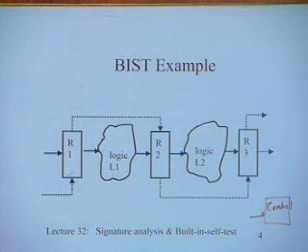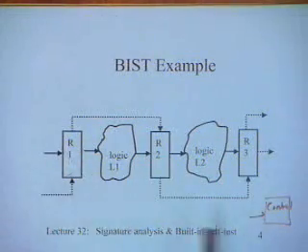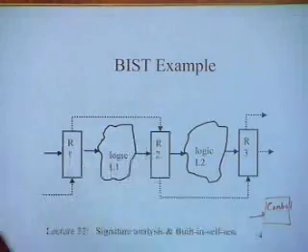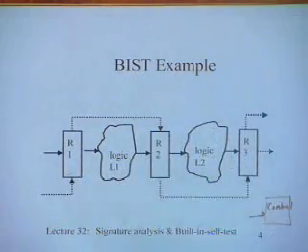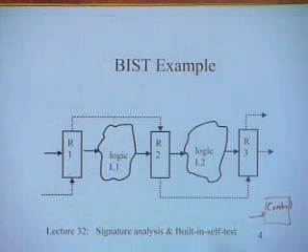Typically the way the design community works is you do the design and then introduce the testing on top of it. That is, you make the design, then you replace these registers, introduce the scan paths, and only the final placement and layout you do after introducing that. But increasingly people are also looking at techniques called design for testability. We are not going to talk about that in this course now. But basically the advantage is you can try to integrate it so that your testing overheads later on become smaller.